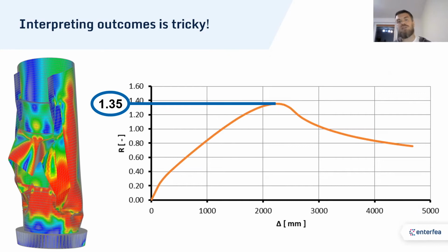And you can say, okay, if I would multiply my load by 1.35, because on the right, you don't see the load because, load on a chimney is a rather complex thing. There are a lot of forces in a lot of directions. So instead, I applied the loads and simply multiply them by small number, then bigger number, then bigger number, then bigger number. This is called load multiplier. And it actually makes sense. If I would increase my load 35%, the model would fail. So first of all, I'm good, right? The load on 1 is still okay. The model would not fail. And this is why this chimney actually stood and worked, right?